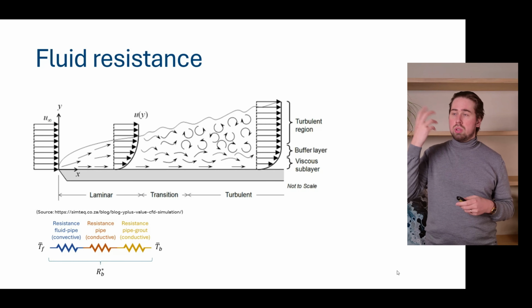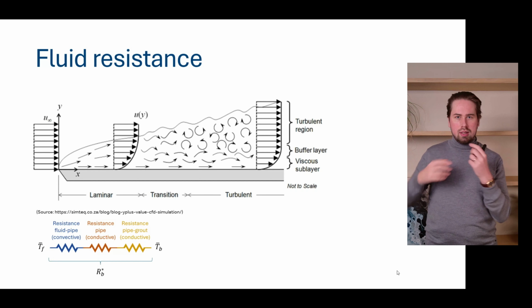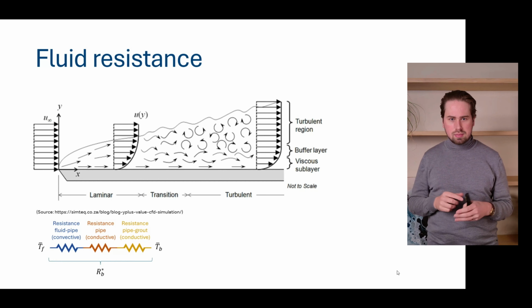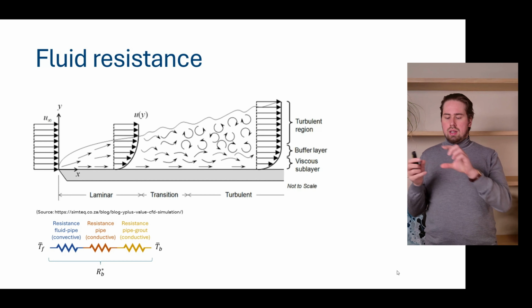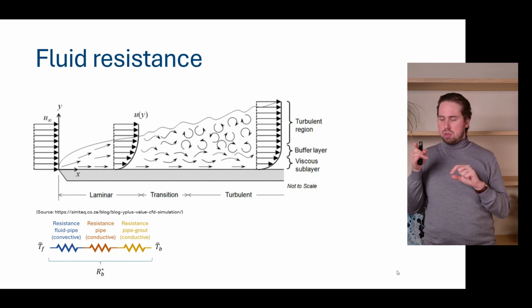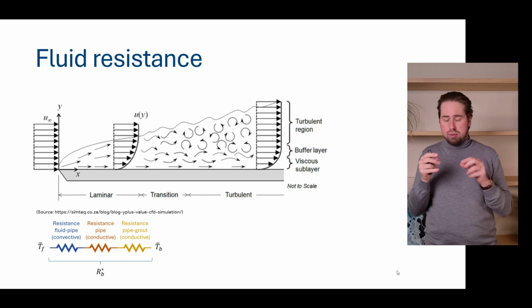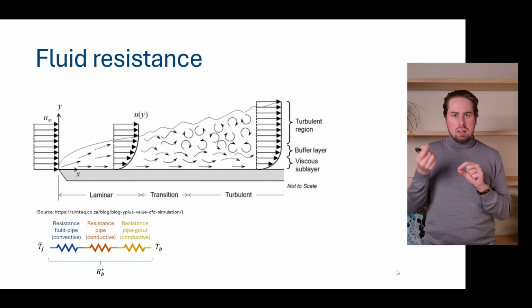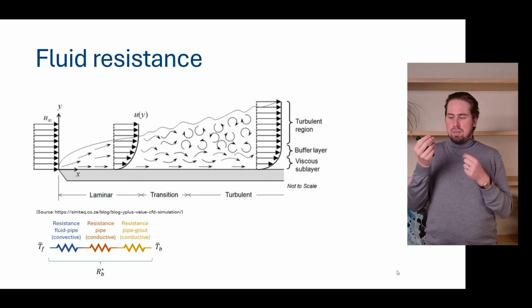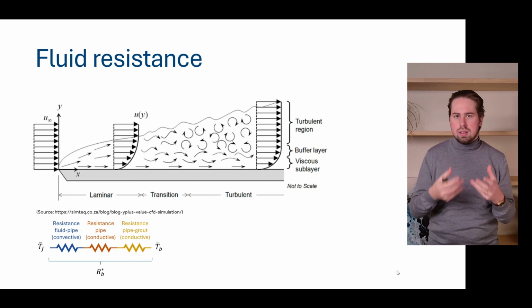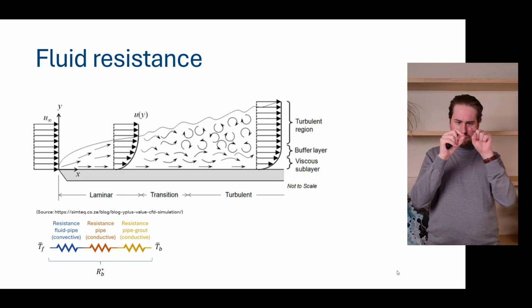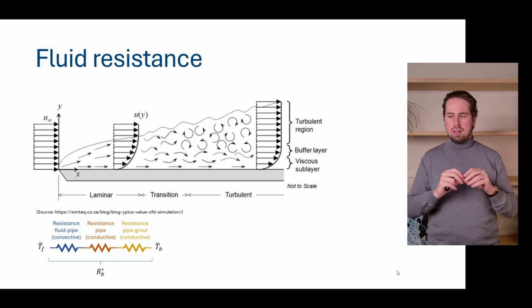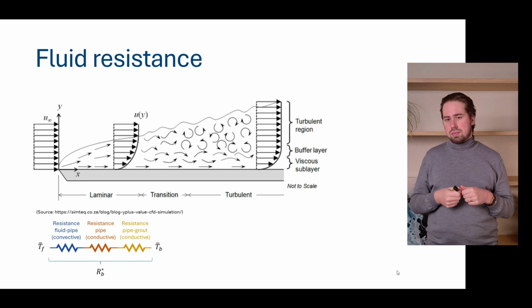If you, for example, also look at the clouds, it's also very turbulent. It's going all over the place. And when we think about heat transfer, if we have a pipe where the fluid is beautifully laminar, the droplets in the middle that also carry some heat never touch the borehole wall. So it's really hard to transfer heat in this sense, because the heat needs to travel through all these different layers before it can actually reach the borehole wall.